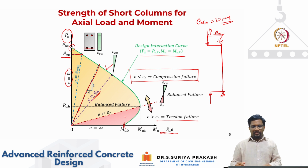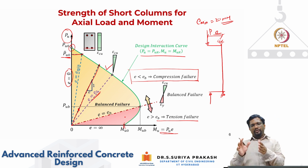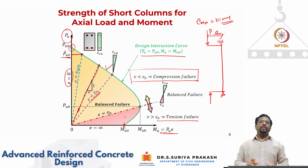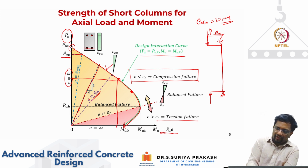Okay, so this is the way we can classify how a particular cross section is going to behave under different combinations of axial compression and bending. And this green curve we have drawn here is called the failure interaction curve. At any point, this curve gives the combinations of P and M the section can take.